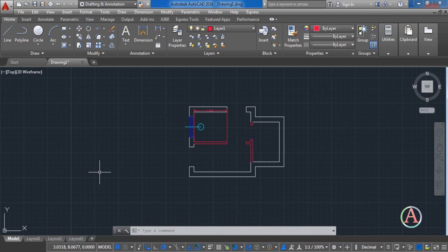The last thing that I want you to do is to go below and click the link to download the exercise. Then create two new layouts. Name the first layout clean floor and the second dimension. In the first paper space I want you to freeze the lines which are not walls, and in the second layout I want you to put the dimensions on the walls.